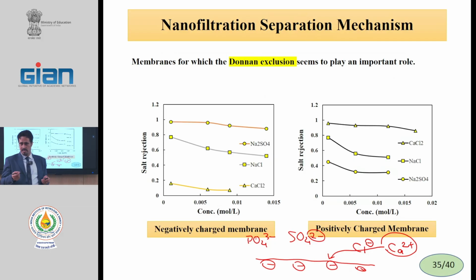Therefore, in the lab, if you have a nanofiltration membrane, with a test of these results, you can find very easily whether this membrane has negative or positive charge. But for measurement of the membrane surface charge, we usually use a zeta potential device. But this simple example can show whether our membrane is positive or negative.